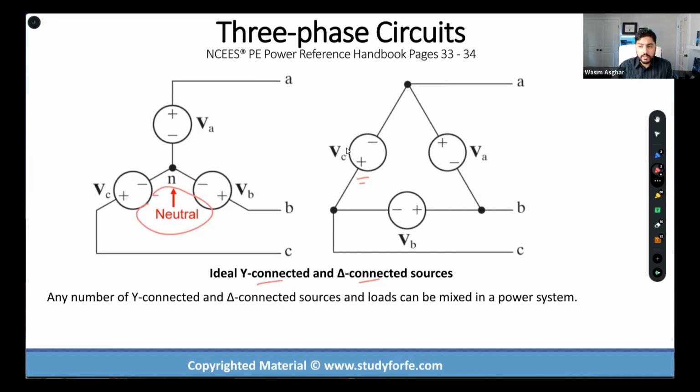They cannot provide reactive power. In fact, they themselves need to be provided reactive power by an external source in order to energize a magnetic field, right? A synchronous generator does not require the magnetic field to be set up externally. Strictly speaking, depending on how you start it and how you configure it, synchronous generators are actually a source of reactive power, and they can deal with both real and reactive load. That's why we deal with synchronous generators instead of induction generators.